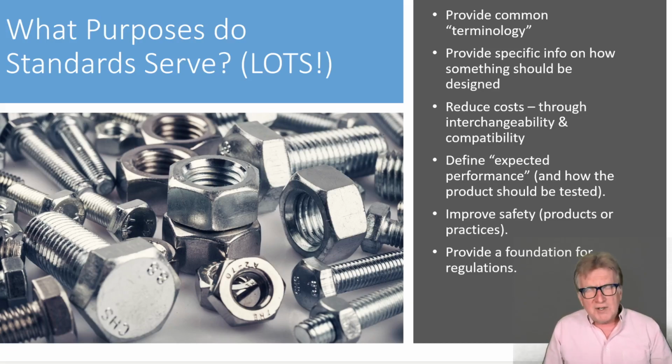We also want to make sure, as I talked about with nuts and bolts, if I buy a bolt, I want to make sure that a grade 5 bolt of a certain dimension has a certain tensile strength and other types of requirements to handle the forces that we're going to be putting on that particular fastener. And we also talk about how that product might actually be tested before it gets put out into the market.